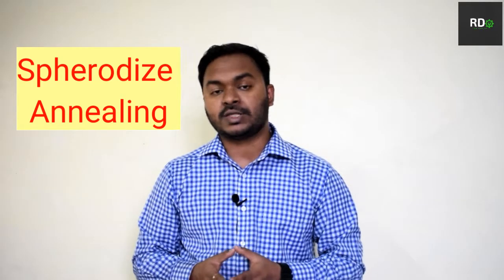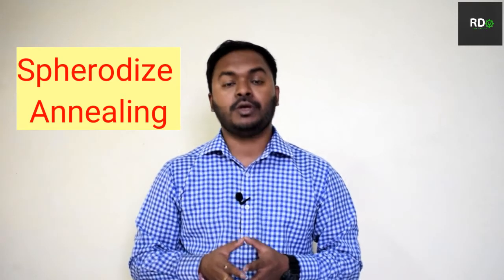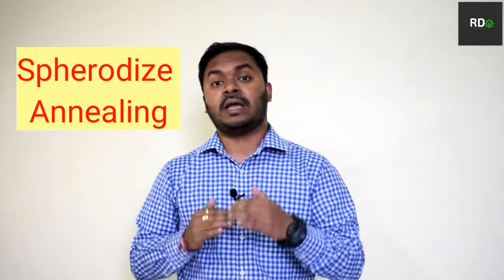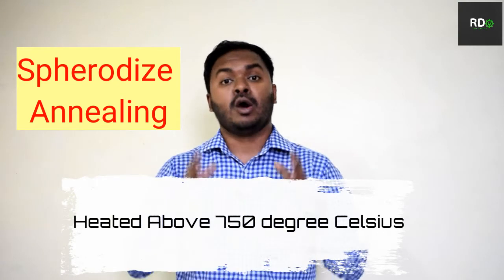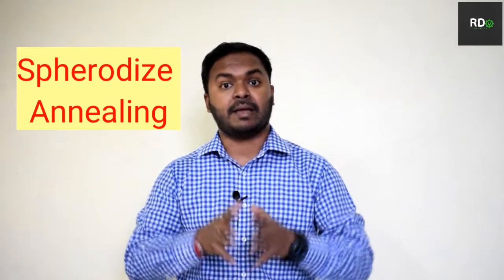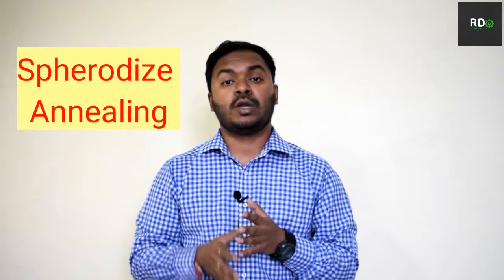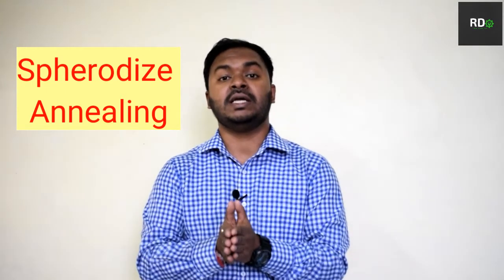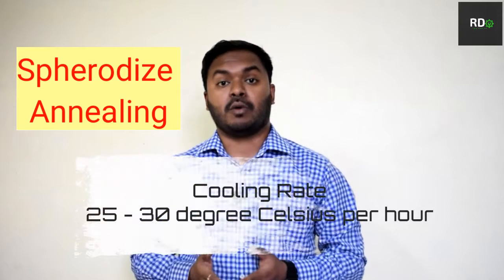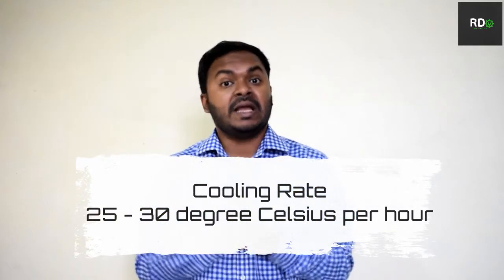In the third type, that is the spheroidized annealing, we treat the material at a temperature of more than 750 to 770 degrees Celsius, then hold the material at that temperature and slow cool to 600 degrees Celsius at a cooling rate of 25 to 30 degrees Celsius per hour. It is mainly done to increase the machinability of the material.